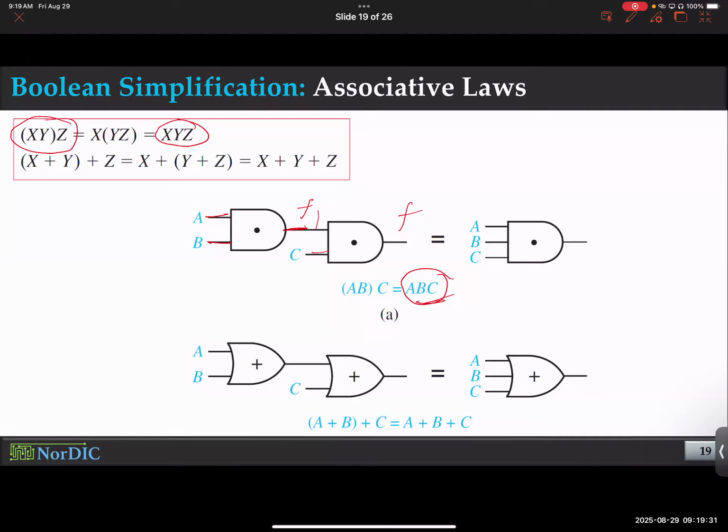The building blocks are, as you can imagine, for the logic side, gates: NAND gate, NOR gate, XOR gate, blah, blah, blah. But don't feel like, oh, there are just a few gates. There are different flavors of NAND gate. There are two input NAND gates, three input NAND gates, four input NAND gates, and they have pros and cons. You might be wondering, if I could handle three inputs at a time, why would I even bother having two input gates? These are design decisions, and I'm not getting into the detail of it. I'm very tempted to. So the more inputs you handle simultaneously, the slower things get.